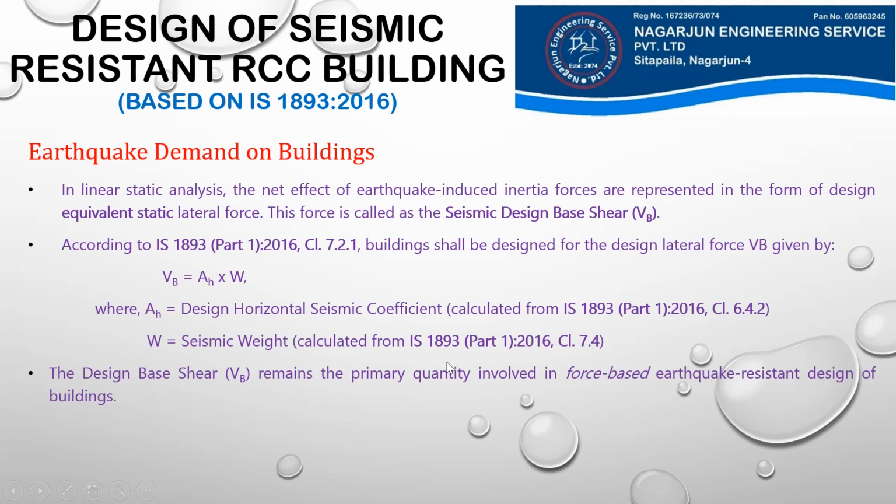The design base shear remains the primary quantity involved in force-based earthquake-resistant design of buildings. We can design any structure either based on the forces that are applied on the structure or based on displacements that are produced in the structure. Since we calculate a design base shear in this linear static analysis, it is a force-based method of design.